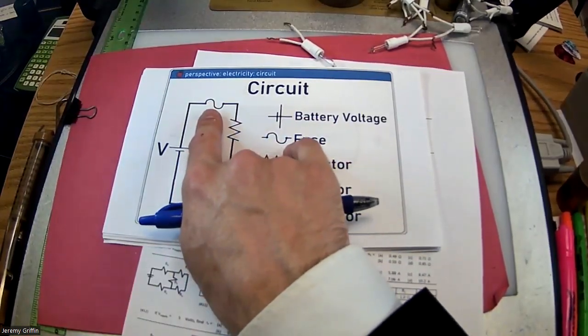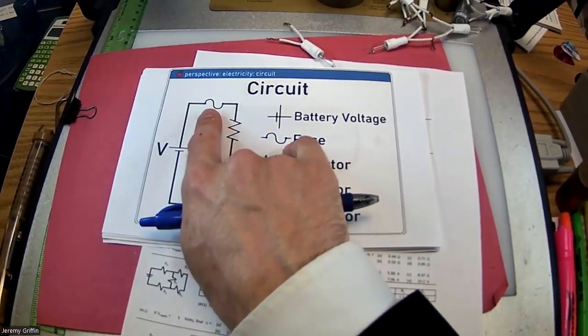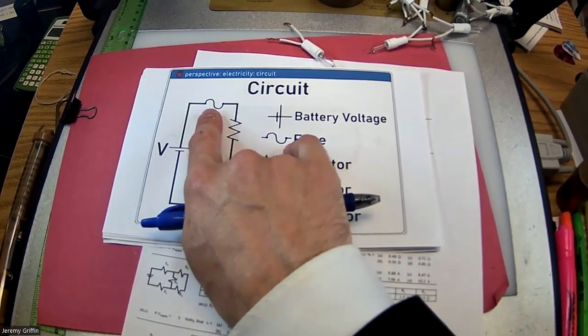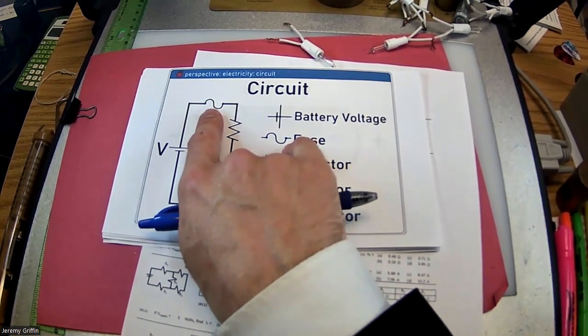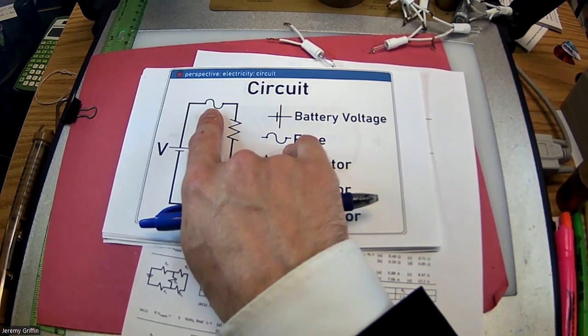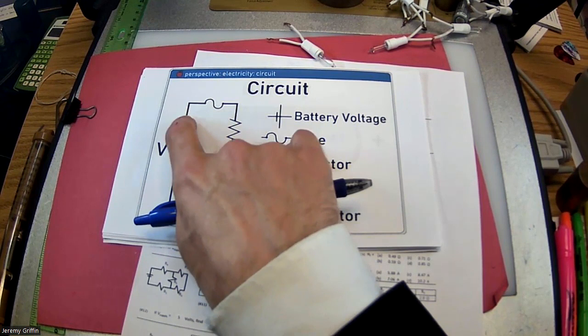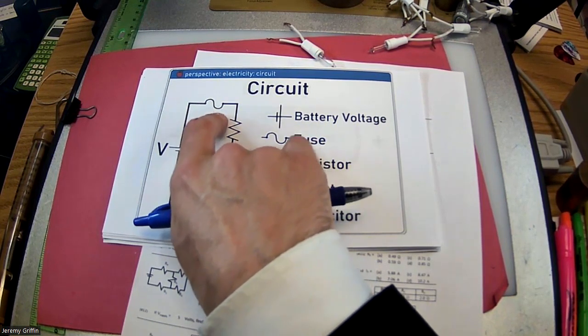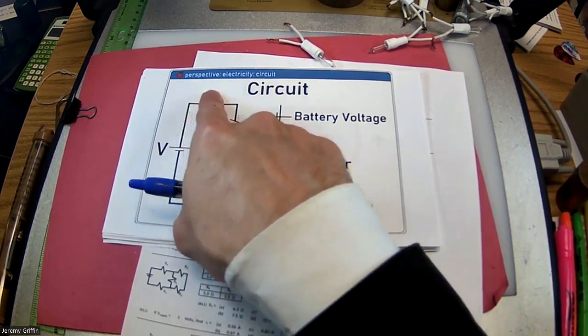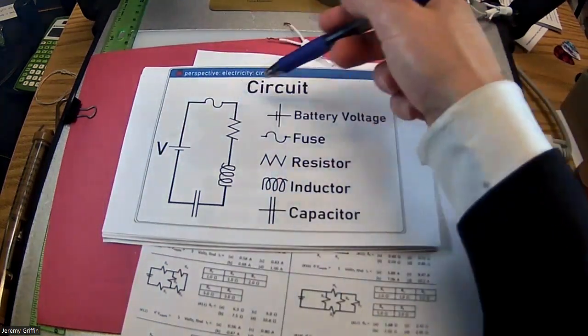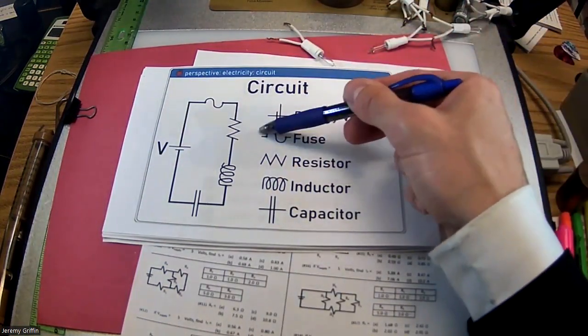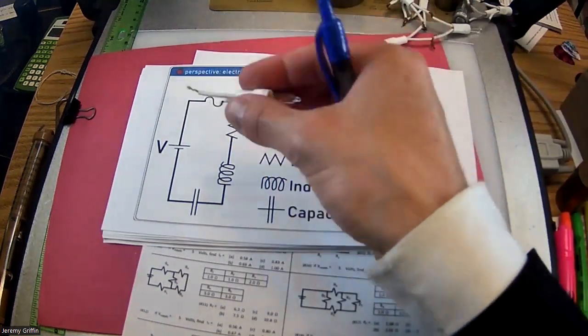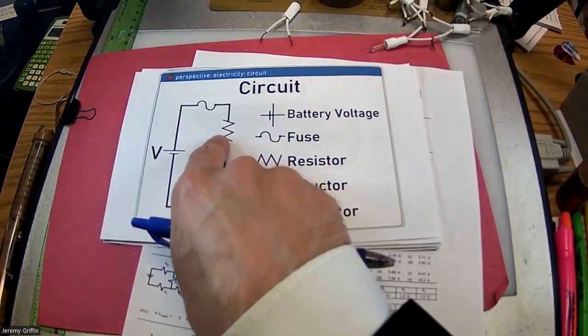Let's say you step out of the shower and you go to plug in something, and you're accidentally touching the metal bit as you're plugging it in, so that you're making contact with it, and then the current wants to flow through you. Which could give you a pretty good shock. That'd be bad. So if the current starts flowing through really fast, then this will blow, and then it'll open the circuit. So you want to connect this in series, exactly as shown there. Here's your resistor. That's like these bulbs. So that's most of what we care about here.